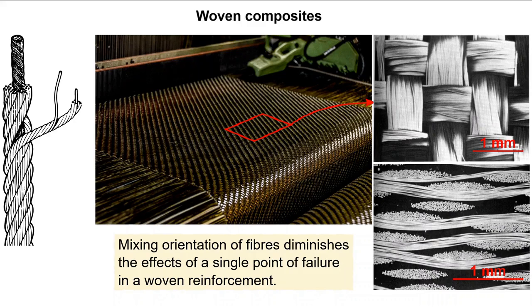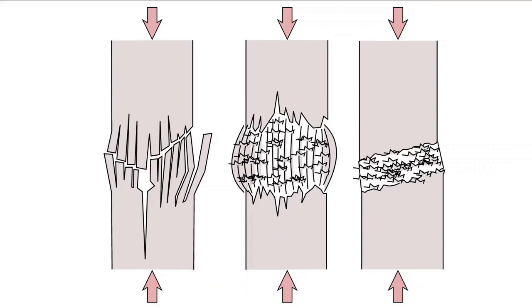So if you take this type of arrangement and drive a Formula One car into it, as you might imagine, you get a lot of potential failures all at once. Rope and cloth still hold good analogies for woven composites. Both rope and cloth are not intended to be loaded in compression, and being embedded in a matrix only helps to a small extent.